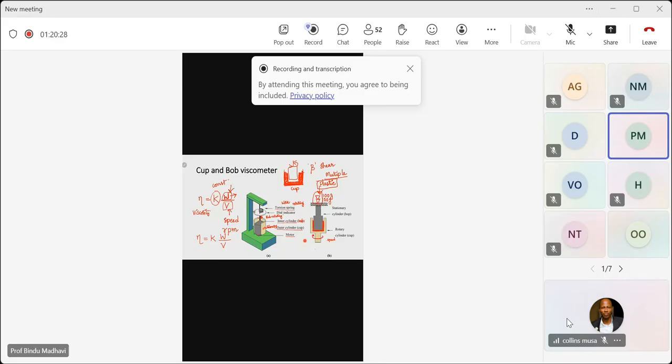What is the significant difference between the plastic systems and Newtonian systems? The yield point. What is that point? Yield point. So plastic systems don't show any movement. They don't allow any rotations until they reach the yield point. So already the system is stubborn. It will not allow any movements until it reaches its minimum amount of shear stress.